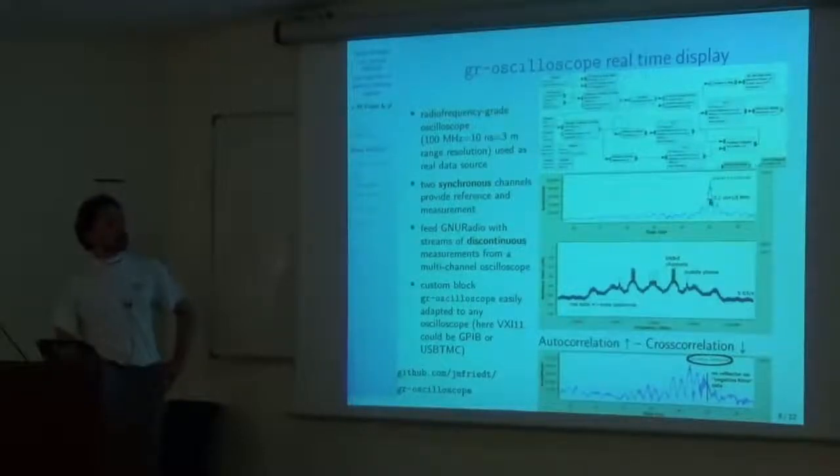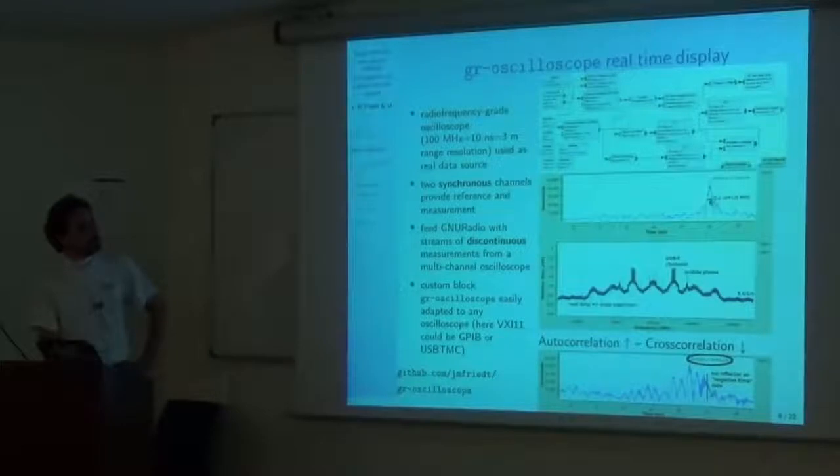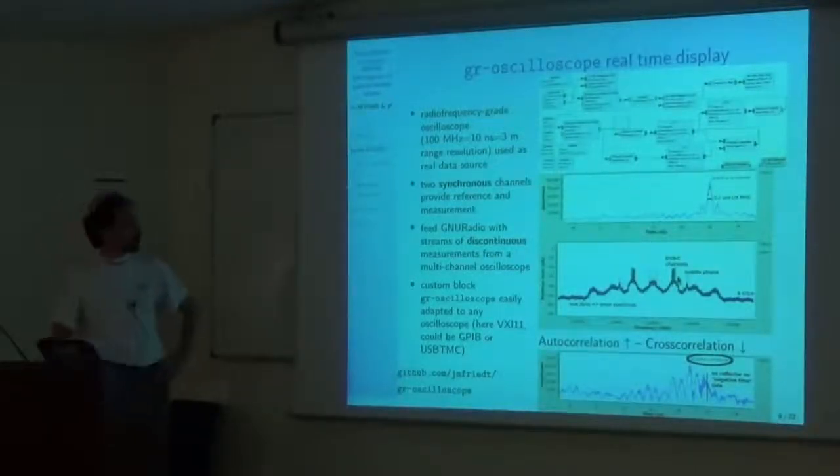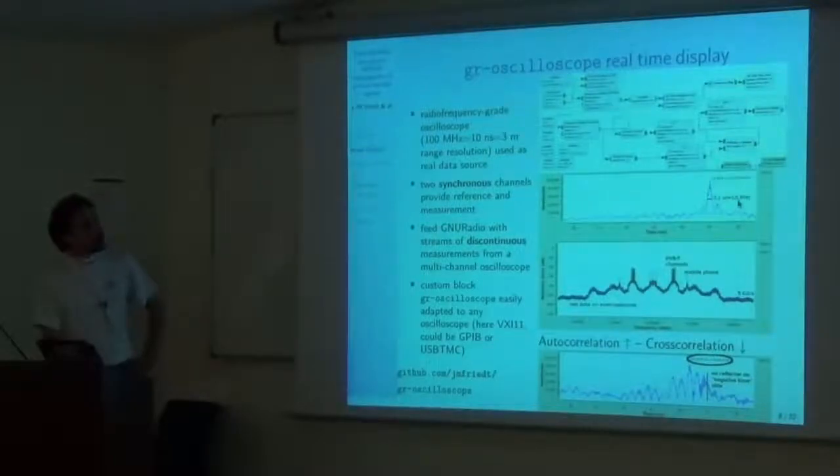And if you take the autocorrelation of the signal, well, autocorrelation will show you a peak whose width is the inverse of the channel bandwidth. So if you have 5 megahertz channel bandwidth, which is the channel width in Japanese standards, you have an autocorrelation which is 200 nanoseconds. 200 nanoseconds is the inverse of 5 megahertz, and 200 nanoseconds will give you about 30 meter resolution, sorry.